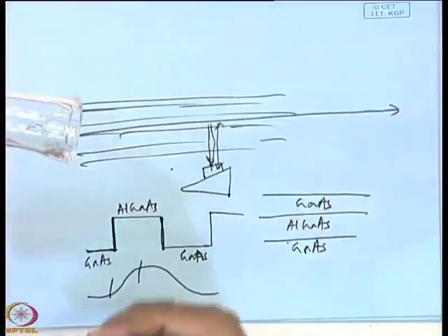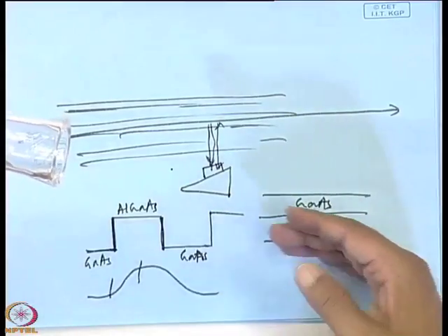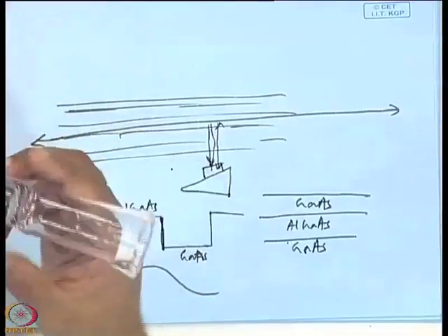When the whole growth is finished, using aqua regia you can clean this thing, so that there will be no aluminum, no gallium, no arsenic. But when you are preparing the layers, during the growth you cannot clean this reactor. So, there may be some trace amount of aluminum or other materials; here we are taking the example of aluminum, it can be different types of materials also.